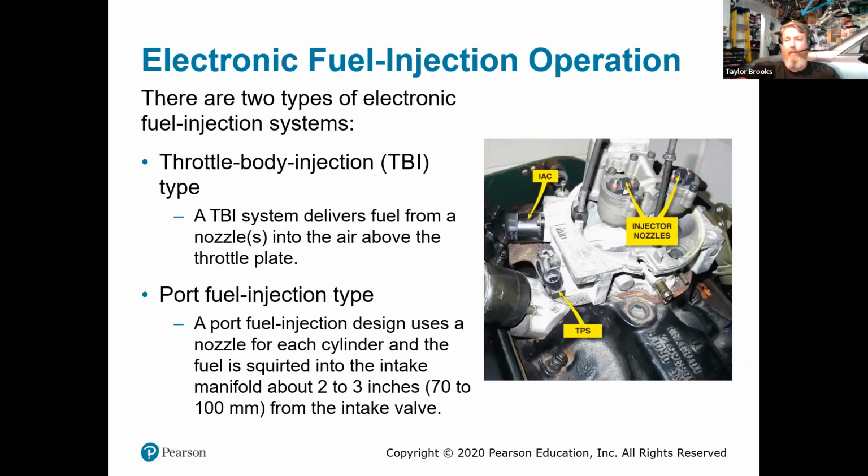In fact, I converted my 1964 Ford to fuel injection. I didn't have to do anything to the intake manifold. I literally was able to take the carburetor off and put the throttle body on. I had to have sensor inputs, but in terms of designing or remanufacturing how the intake manifold was shaped, it didn't matter.